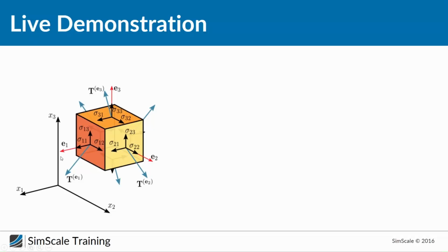The idea of principal stress is that in the end every three-dimensional stress state can be represented by three principal stresses, one in each direction. And that allows you to understand three-dimensional stresses without going too much inside the simulation. So it helps you to understand basically how stress is going through your model.